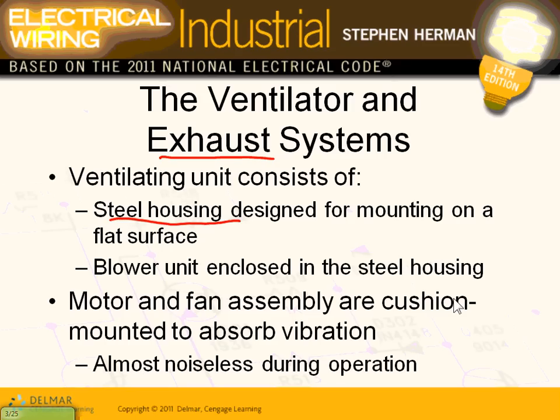What's my job? Do 2 things for them. Number 1, provide a feeder for them. And number 2, provide a fused disconnect to power them. Most of the time, guys, even controlling them is beyond our expertise because it's tied to the whole heating, cooling, and ventilation of the whole building. So most of the time, we provide a feeder to feed them and a fused disconnect or a circuit breaker to protect them. So that's what they're talking about. And this talks about how they house them and the housing and so forth. Noise is a big deal, but we really don't get involved in sizing these in any way, shape, or form. We don't. So I don't want to spend time on that.